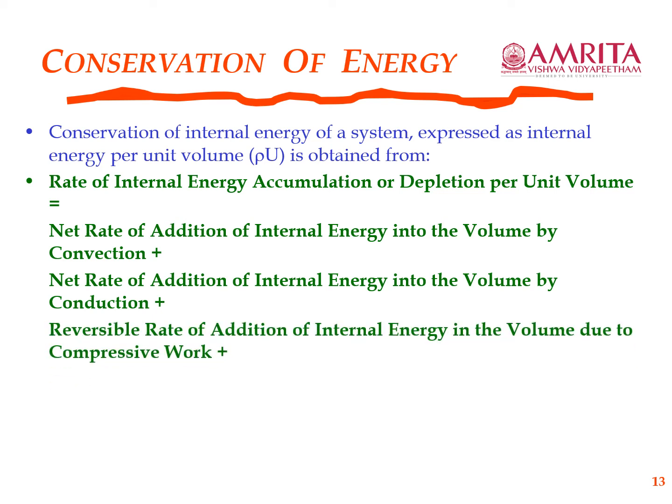And then you have the reversible rate of addition of internal energy in the volume due to compressive work. What does this mean? This is really when you have a compressible fluid. Now that compressible fluid may undergo a local compression or expansion, for example compression and rarefaction, when you are trying to propagate sound waves into air or any kind of compressible fluid for that matter, right?